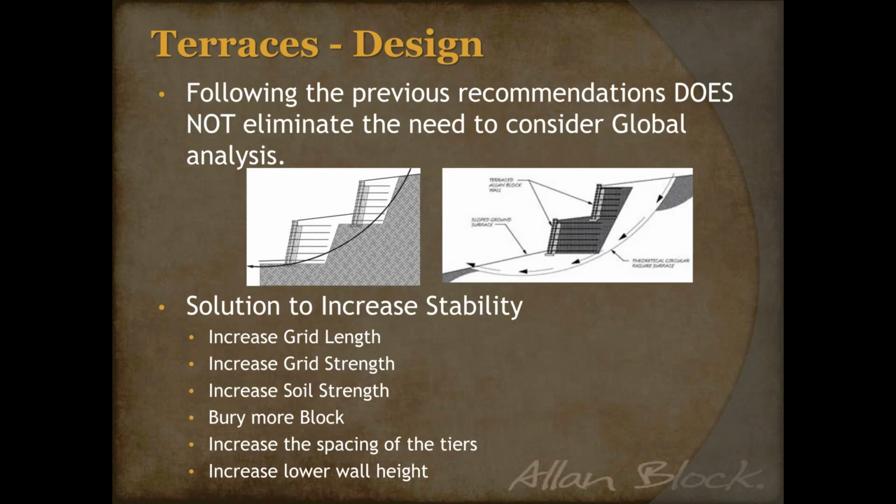So once you've got the terrace walls designed, we do recommend global stability be run for terrace structures. But again, as the engineer of record, that is your decision to make based off of your knowledge of the site and the materials being used. Again, I'll be redundant in this, just like our best practices is, because I want to drive some points home here. You are the controlling engineer on these sites. If you feel like global stability is a concern, let people know and see if you can get that run, either by you or by the geotech. It doesn't matter what our paperwork says. If our best practices says you have to, again, it is your decision. We do not override your decision because you will know it a lot better than we do.